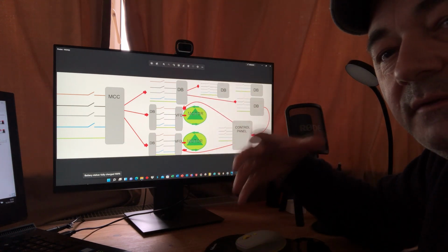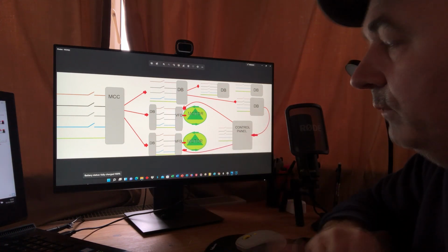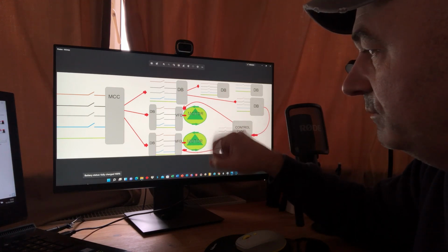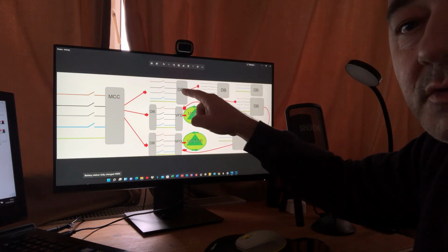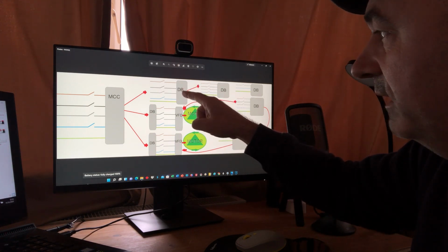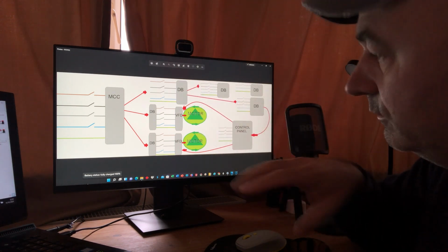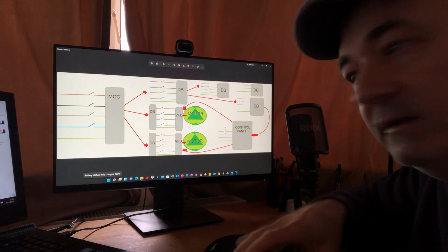So you see you have a tree of power supply, and when you do your investigation you can have a local investigation to see why your motor tripped, but at the same time you might have this distribution board tripped, and then you will have to go step by step to investigate until you reach the core of the problem. I will talk more in detail in another video.